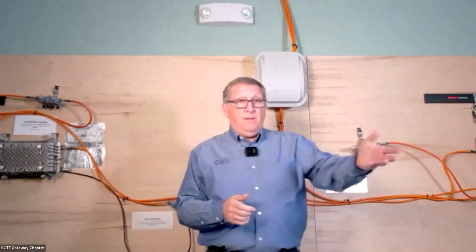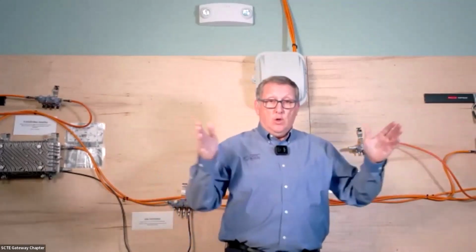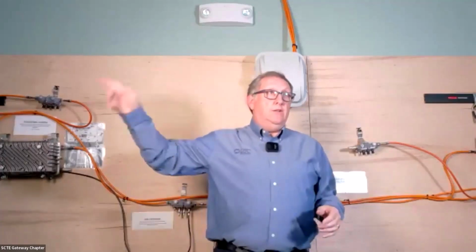Over -5, now you're damaging optics, right? So if you have an SFP that's putting out a +4 and it's going a real short distance to a node, you're going to have to use some optical attenuation to make sure you don't damage your optics. Even if it works when we plug it in, if nothing else, you're prematurely wearing out that receiver.